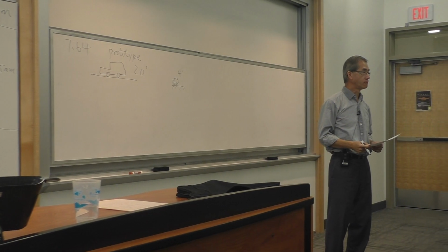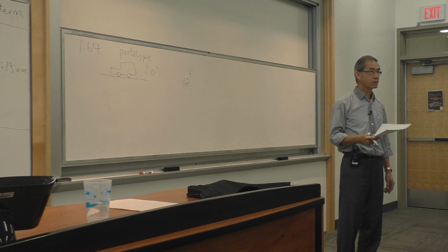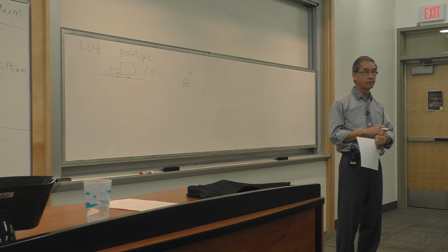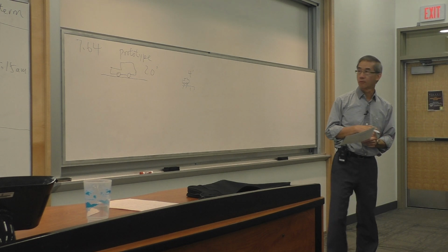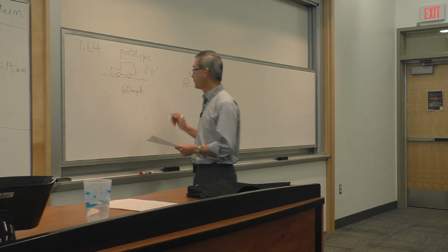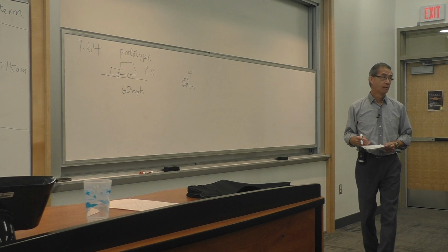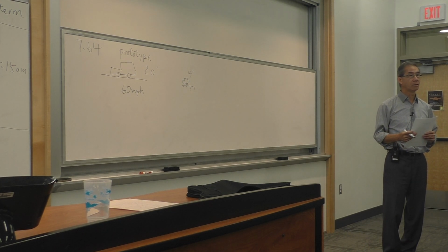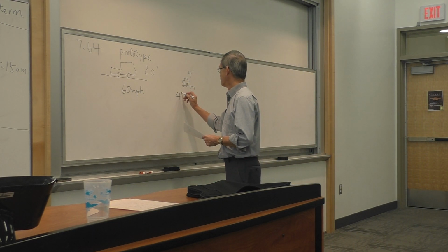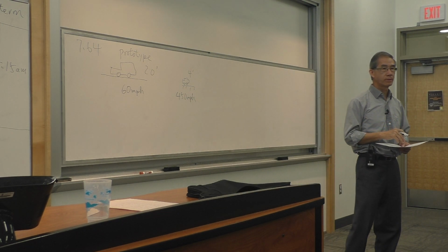What have you learned from this homework? The question asks you, can you feasibly match the Reynolds number? What's your take on that? You've done the homework, right? So to match an automobile at full size at 60 miles per hour, what is the speed in the wind tunnel for a smaller model at 1/5 scale? How fast do I have to run the wind tunnel airspeed in order to match the Reynolds number? The answer is 450. So what's the big deal?